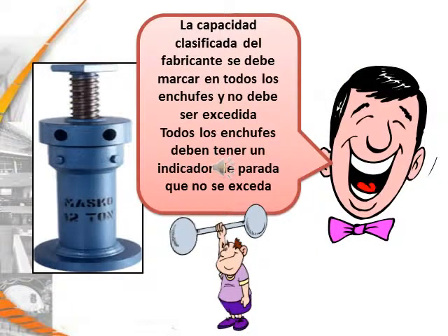The manufacturer's rated capacity must be marked on all jacks and must never be exceeded. All jacks must have a stop indicator that is also not exceeded.